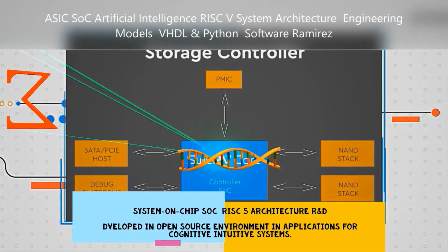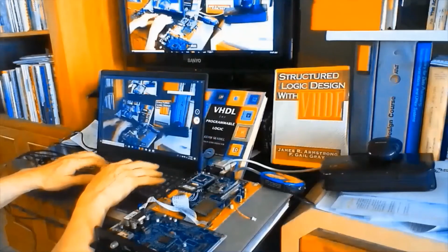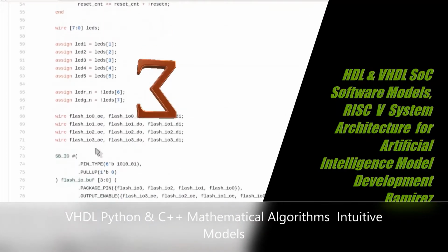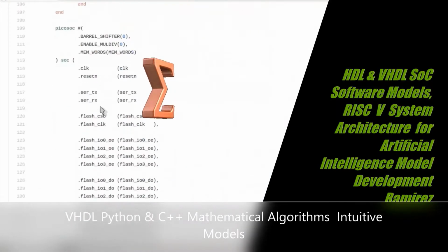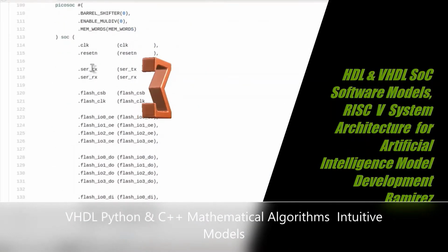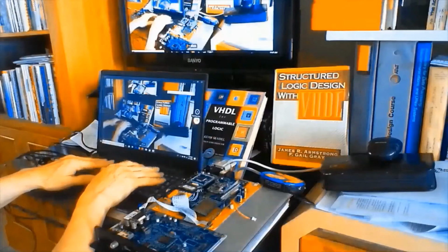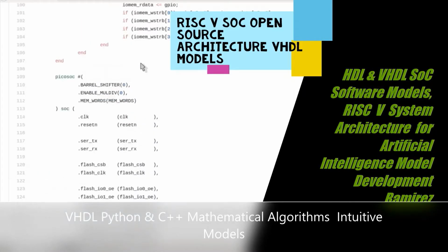In this video, I illustrate the system implementation of the RISC-V system-on-chip subset, showing the major functional units and the major connections between all of these units. All instructions start by using the program counter to supply the instruction address to the instruction memory. After the instruction is fetched, the register operands used by instructions are specified by fields of the instruction.